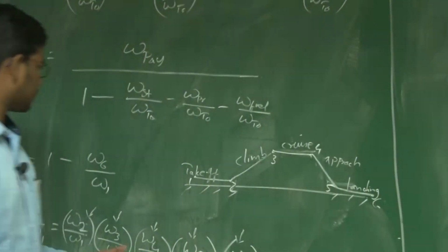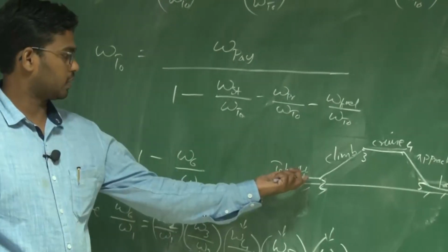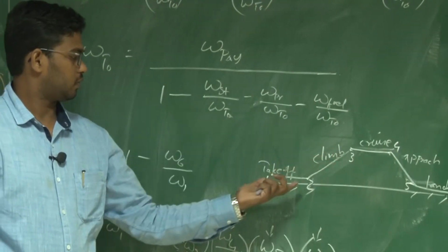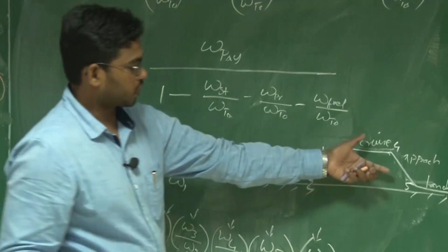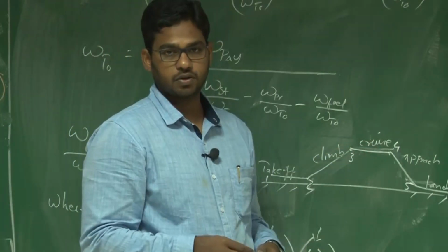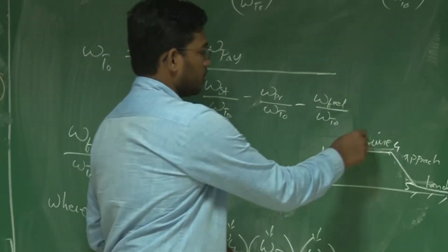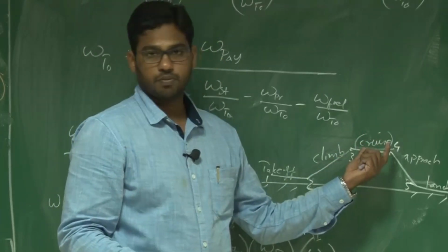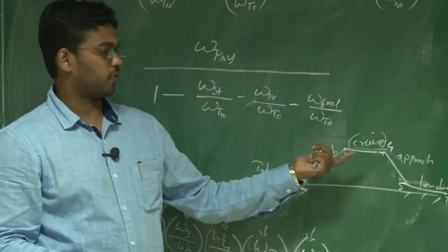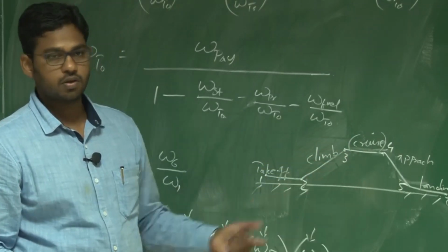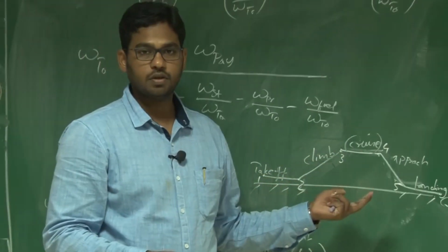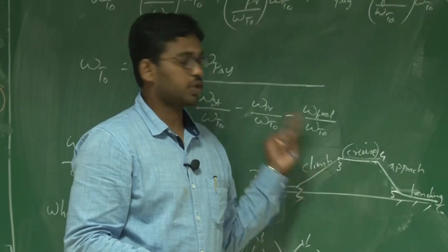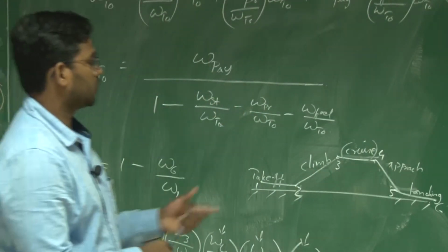Now, we also discussed that for takeoff, climb, approach and landing we have weight fractions from the historical database. So what differs from UAV to UAV or aircraft to aircraft is the cruise profile or the cruise fuel consumption, which mainly depends upon the mission requirements, or the tasks to perform.